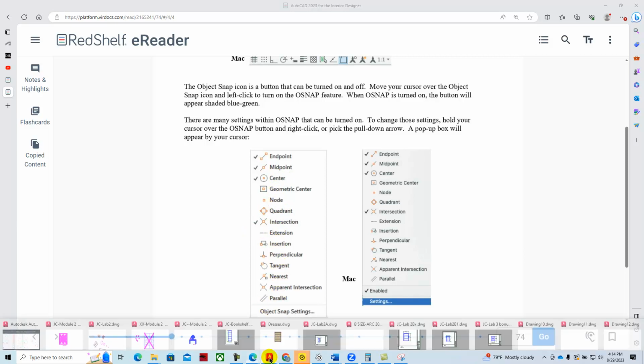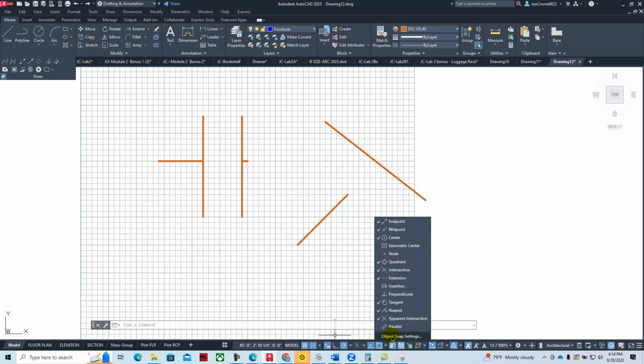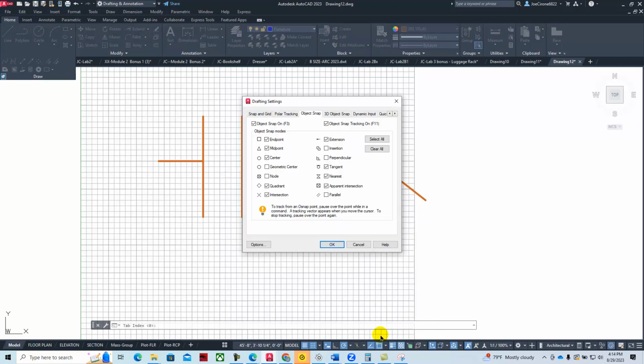And so when we go into our drawing, if we look at our O snaps in our object snap settings, the ones with the check marks are running. So we can say endpoint, midpoint, center, and then if I turn these other ones off, it won't acquire those.